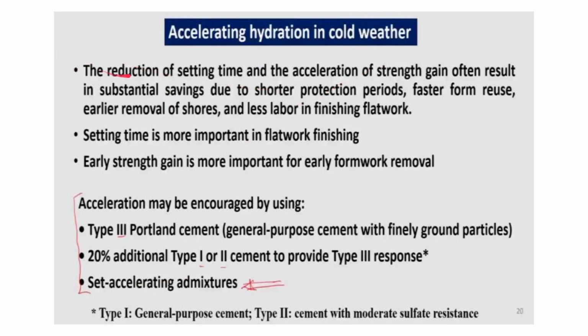The reduction of setting time and the acceleration of strength gain often result in substantial savings due to shorter protection periods, faster form reuse, earlier removal of shores, and less labor in finishing flat work. These are some of the main advantages of using accelerated hydration.